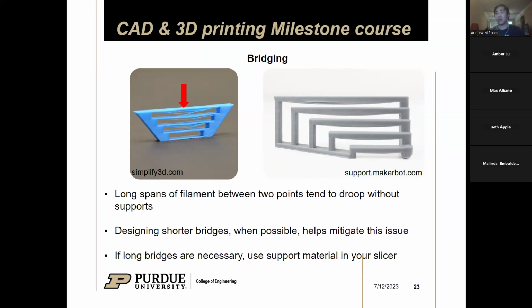If you have questions about your final and how manufacturable it is, feel free to send a photo of it to me and I can give you feedback. But a lot of it is just using your judgment. And your judgment may improve over time if you start to use printers more and get a better feel for what printers can do. But my general rule of thumb is 2 or 3 millimeters for a minimum, and you should be golden.